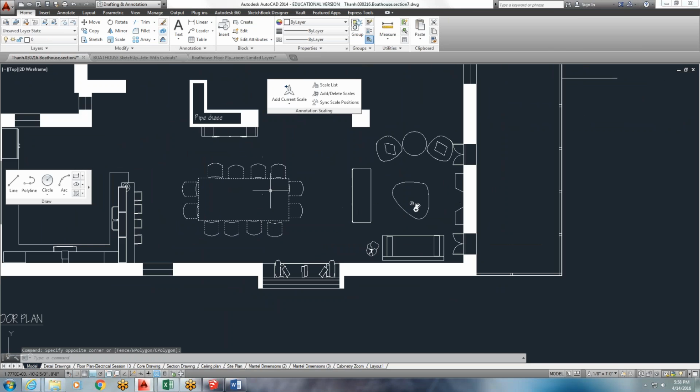So at this point, it depends on how you want to do it, but the more things are blocks, the easier they are to move. Now, another thing to remember is the moment things are blocks, the harder they are to edit. So you want to do all the work on your blocks, the cleaning up of the lines, before you make them blocks. If I'm happy with my dining table, then I could go ahead and type or select it,